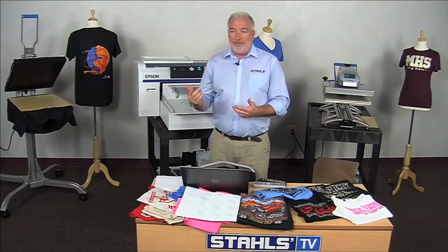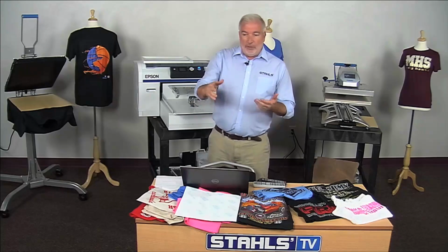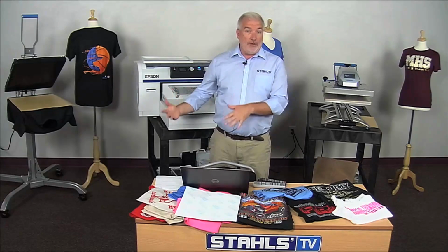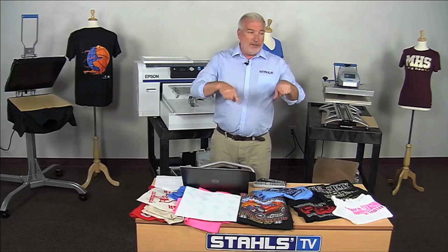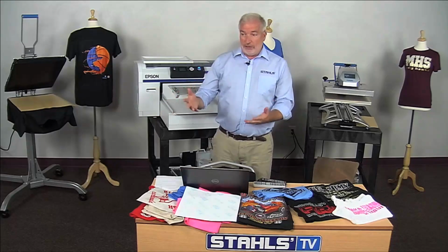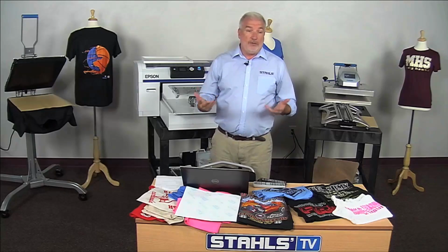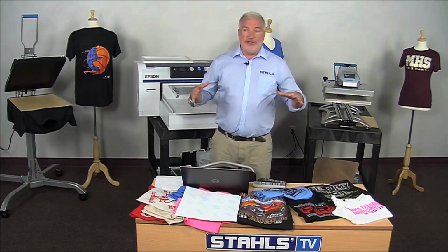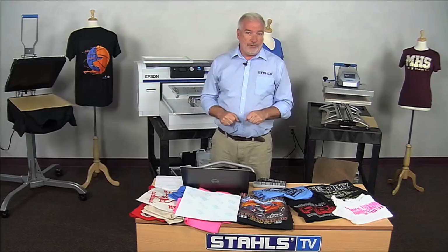You can also get what they call feathering, where the white ink will hit those fibers that are standing up, and then they'll lay down when you're doing the CMYK or the color process. You get the little white lines within the design, and if you've looked closely at some of those shirts, it's really not the printer's fault. It's not the direct-to-garment printer's fault, or the ink. It's usually the case of the pre-treat in the shirt. So in most cases when someone complains that they just can't get good quality out of their direct-to-garment print, a lot of times it's the shirt or the pre-treat and the preparation at that point.